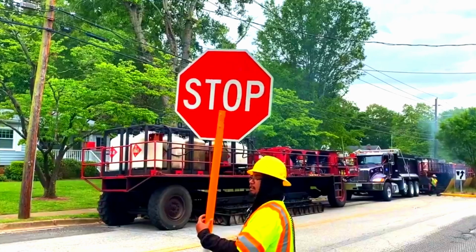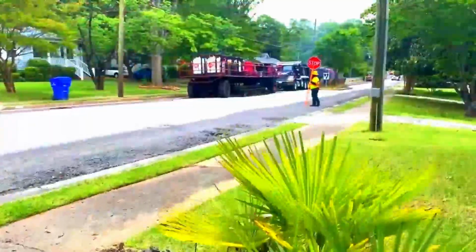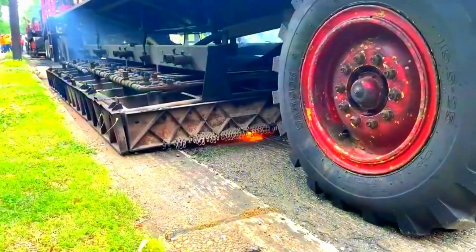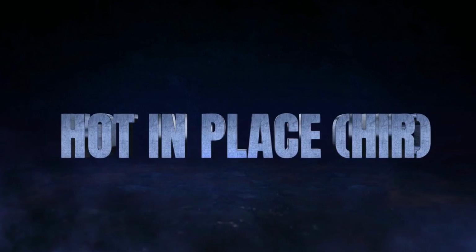Hot recycling is a technique where existing aged asphalt is heated, softened, mixed with fresh bitumen and additives, and then relayed as a new pavement layer. The first method: hot in-place recycling.